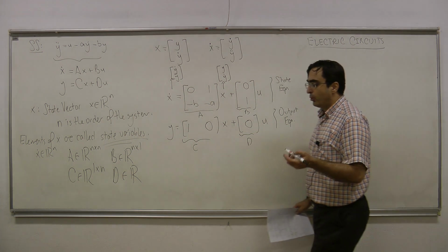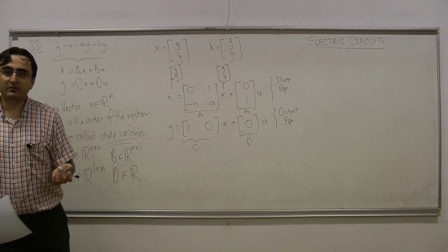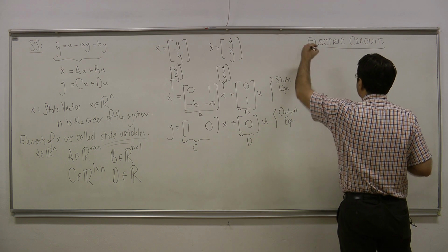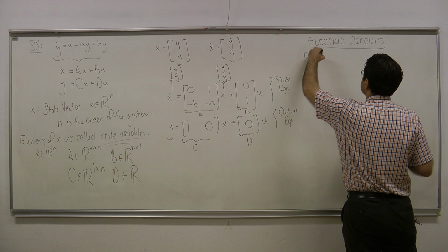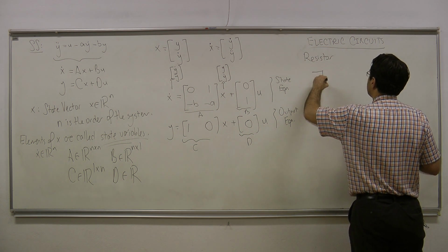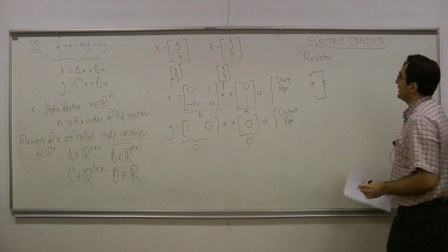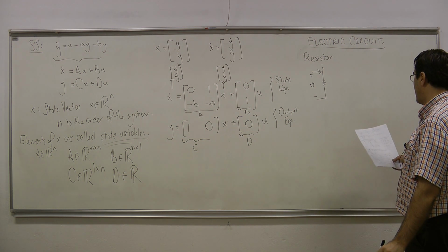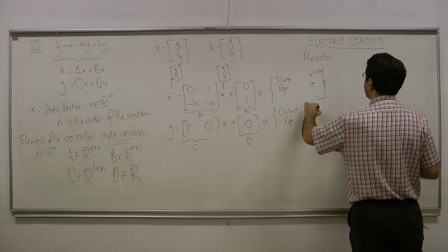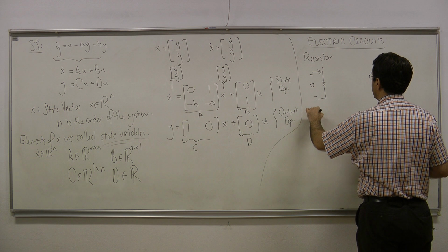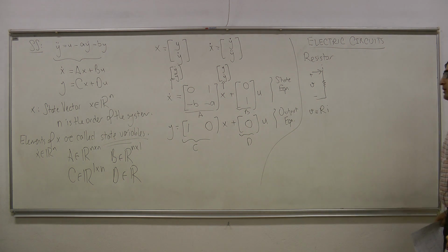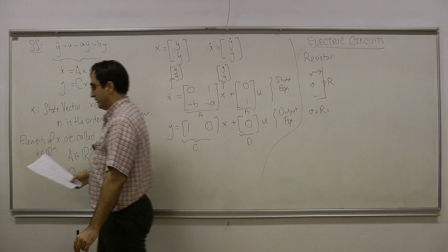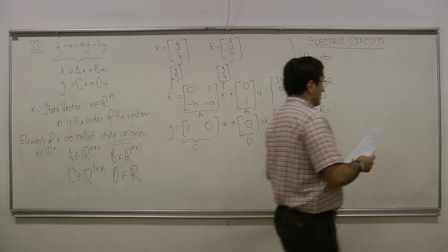So first I will write the components of an electric circuit and their terminal equations. You would probably remember those from high school or from your physics classes in the first year. The first element is the resistor, and it is going to be shown with such a notation. The voltage that we apply is shown by V, and the current that we get as a result is called I. The resistor terminal equation is nothing but the following: V is equal to the resistance value times I. Resistance is shown by the letter R. And then we have the inductor.